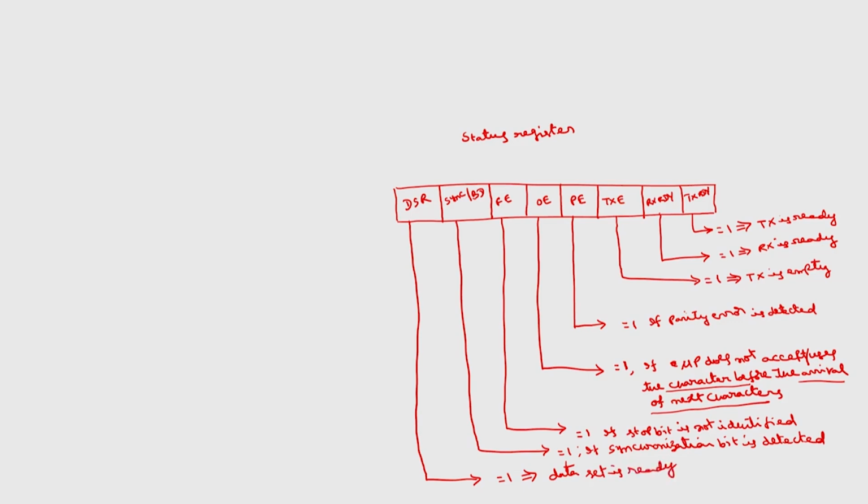This is about the status register. So, the microprocessor can read the status register, thereby it knows the status of various signals. There are two registers, the mode word register and the command word register. The microprocessor has to write something into those to set some specifications, whereas the status register the microprocessor reads. Okay. So, this is about the first block, which is the read write control logic block.